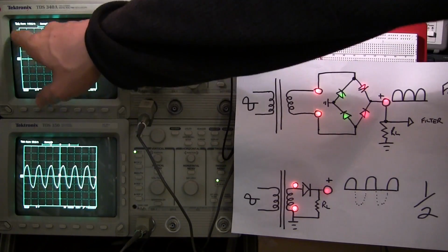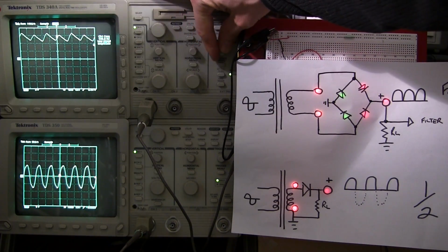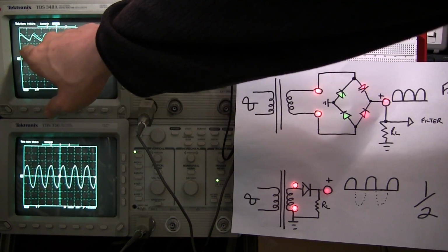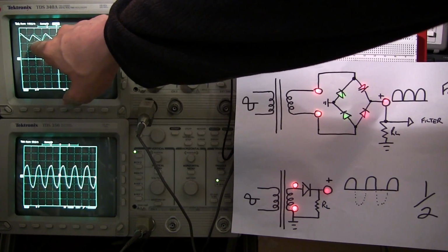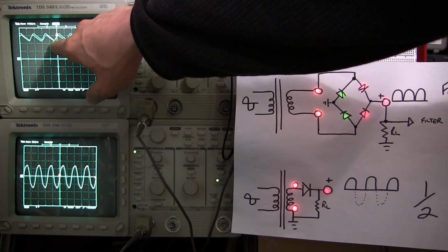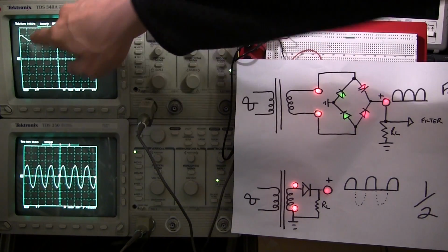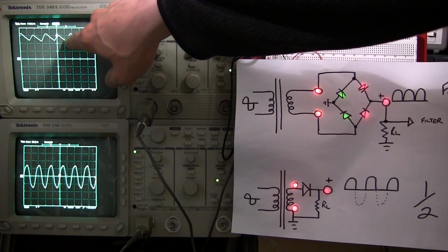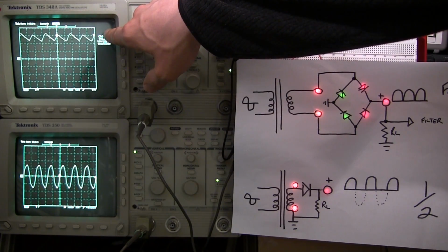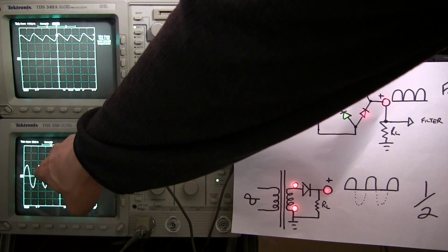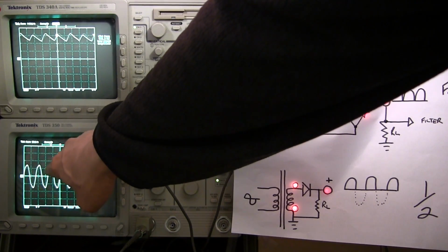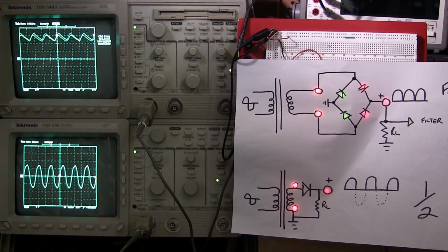And as you can see, what's happening is, move the trigger, steady it up a little bit. So what's actually happening here is this is charging with the cycle, but it doesn't have enough capacitance to hold it as it's going through. So the LED circuitry, and there's a resistor in there, is actually pulling this down. So not enough capacitance, so we still have quite a bit of ripple here. All right. So you can picture that as it's coming to the top here, and then it doesn't have enough staying power, so it's draining the capacitor off, and then it's riding the next peak up and then doing the same all along here.